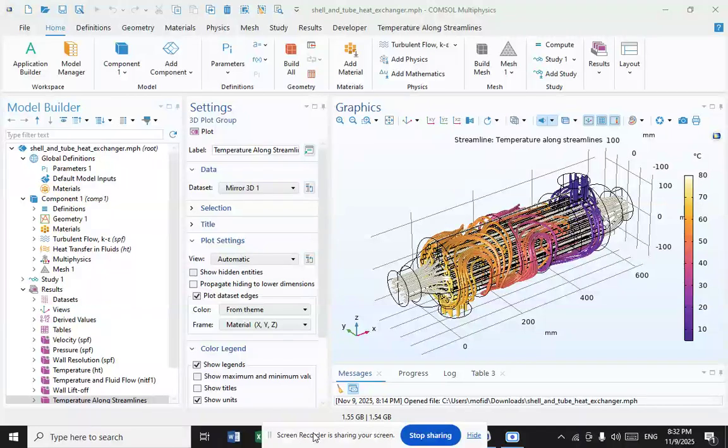Heat exchangers are usually cheaper when they have a smaller shell diameter and a long tube length. Thus, typically, there is an aim to make the heat exchanger as long as physically possible whilst not exceeding production capabilities. However, there are many limitations for this, including space available at the installation site and the need to ensure tubes are available in lengths that are twice the required length so they can be withdrawn and replaced. Also, long thin tubes are difficult to take out and replace.